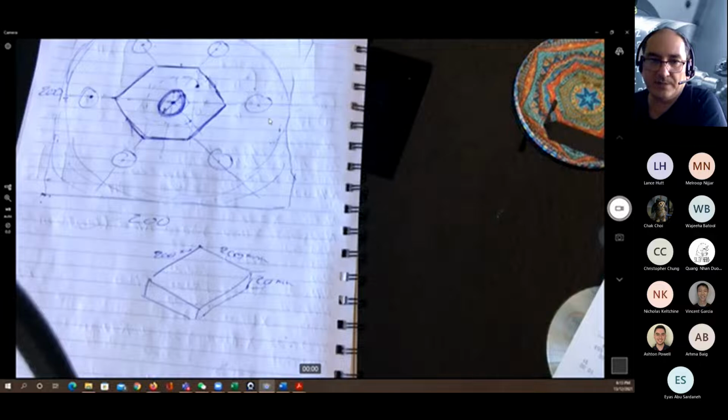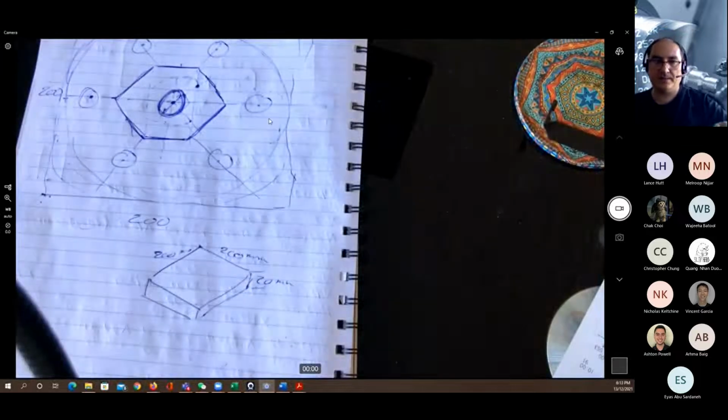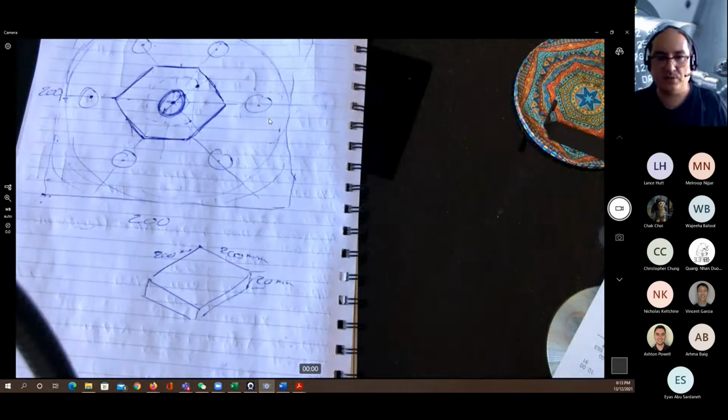How to hold such a shape on the milling machine? On the milling machine, we have a table. The table usually has slots. These slots have a T shape. So within this slot, I can slide bolts. These bolts can be used either to hold the part directly if it does have holes, or I can use these holes and the bolts to use clamps. A clamp is a device that holds the part from the side while I do the machining.